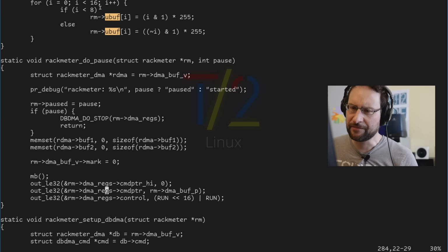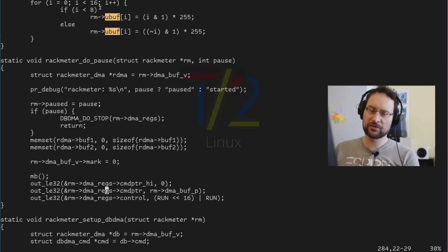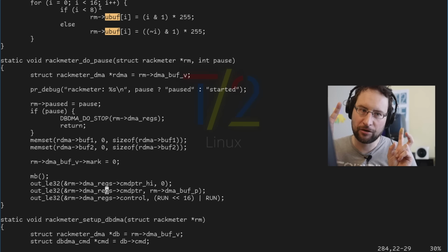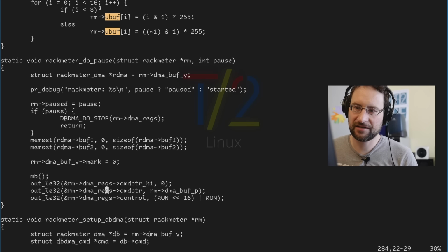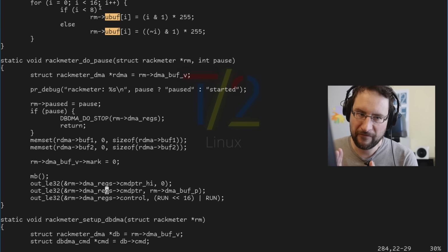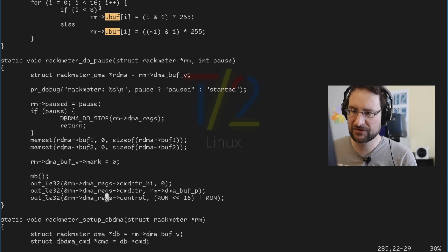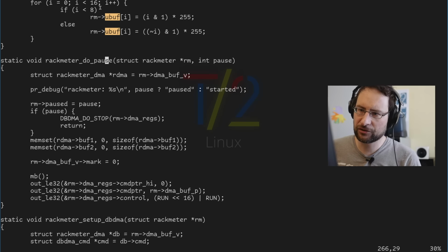Okay, pause. I think, alright, so I think I looked into the original code already. Because this original code does DMA, for power efficiency reasons Benjamin Herrenschmidt went the extra mile of actually stopping DMA. Like if the load is 0 and no LEDs are shining, he went the extra mile of stopping the I2S DMA transfer. That is probably what this is about. So I mean, we could actually do the same.